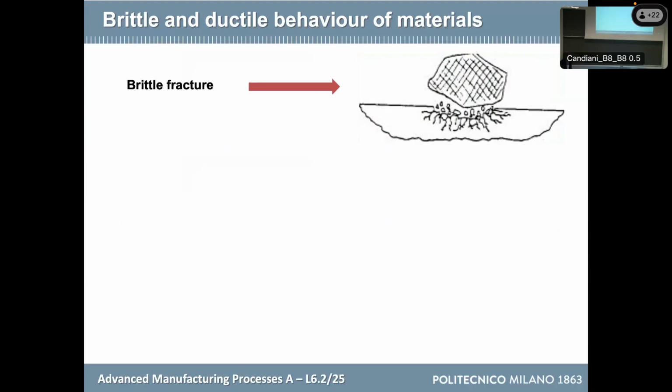Now, let's see what happens when the abrasive touches the material. And we have said something when dealing with ultrasonic machining. So now we inherit everything I have already said. But I'm adding here something more. Because when the material is brittle, basically what happens is represented here. This is called erosion. And erosion is particularly effective when the angle of impact is 90 degrees.